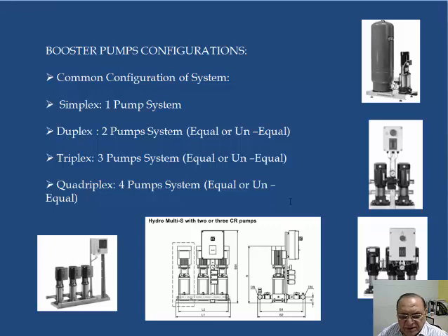Like on first demand, for example, pump number 1 works, on the second demand pump number 2, third demand pump number 3, and fourth demand pump number 4, and the fifth pump remains standby. In case of a problem with any pump, the fifth pump can operate. That logically keeps the wear and tear of the pumps the same.